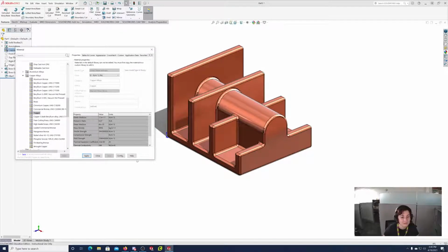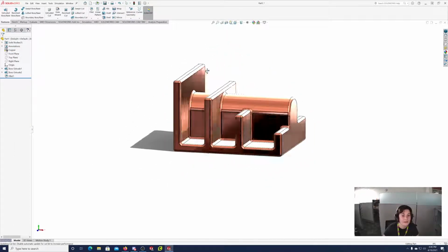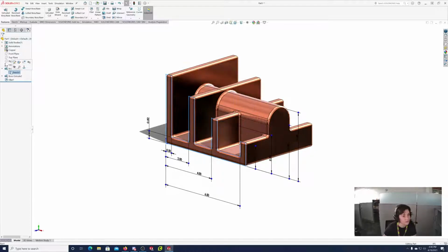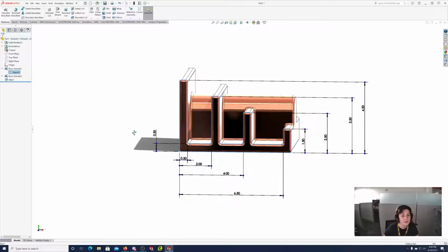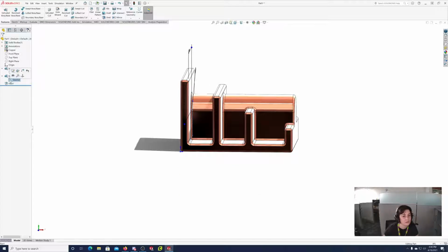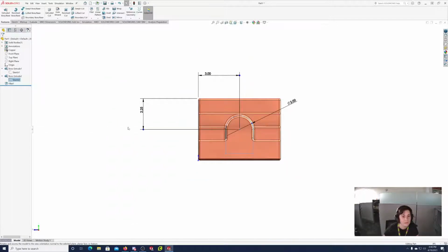Yes, you can. There's a couple things you can do. You can go back into one of your sketches. If you click on that sketch, you can see the dimensions of the sketch. That's the simplest option. You go to the sketch, and you can do that little up arrow where it centers the sketch. Zoom out a little so we can actually see these dimensions.